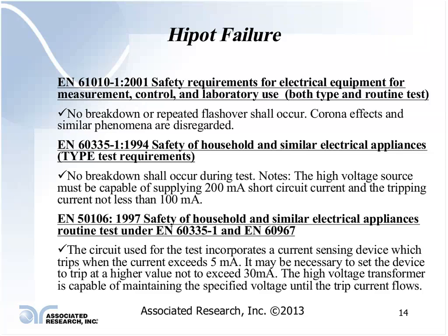Part of the reason behind this is they want to make sure that it is supplying a proper voltage to the device under test, because these tests are normally done for a longer period of time. Again, they want to make sure that the voltage does not sag during the testing process. So part of the reason for having a high current capacity source is to make sure that it is regulated well enough that it will be able to produce this current.